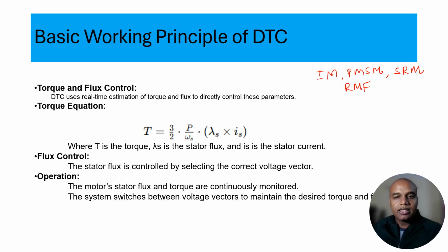Taking that modeling into account, the torque of all these three motors, whether induction, PMSM or SRM, has a relation with lambda s, which is the stator flux, and is, which is the stator current.